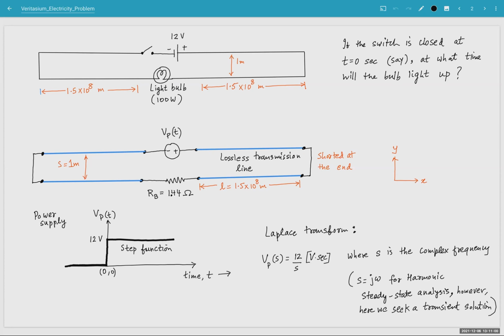What my friend and I both initially thought intuitively was that, for the light bulb to light up, it has to have current flowing through the filament of the bulb, either in an incandescent bulb or an LED bulb. In any case, the current must flow, so that current must be delivered by this battery somehow. And yes, surely it can be delivered through space as a displacement current, because the conductors have a distributed capacitance between them.